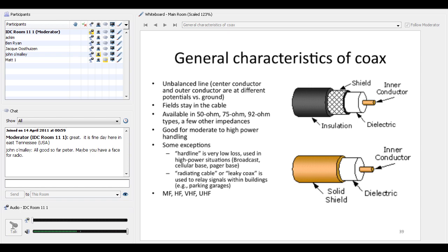It's got an insulator, it's got a shield, it's got a center conductor. So the shield is ground, the inner conductor on the right-hand side, that's hot. So there's ground, there's hot, there's not hot. That's what a cable looks like. Now specifically, there are these things here. This, let's try to color it in, that's a dielectric. It's like a type of plastic or rubber or something.